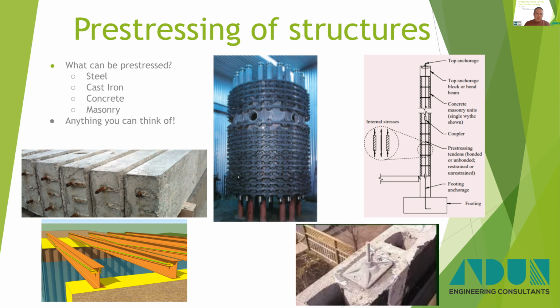Masonry can also be pre-stressed. With a foundation and your anchorage coming up to the top of the wall, you can tighten up your anchorage, which puts a pre-stress into the masonry wall, which gives it additional bending capacity. And there you can see one in practice.